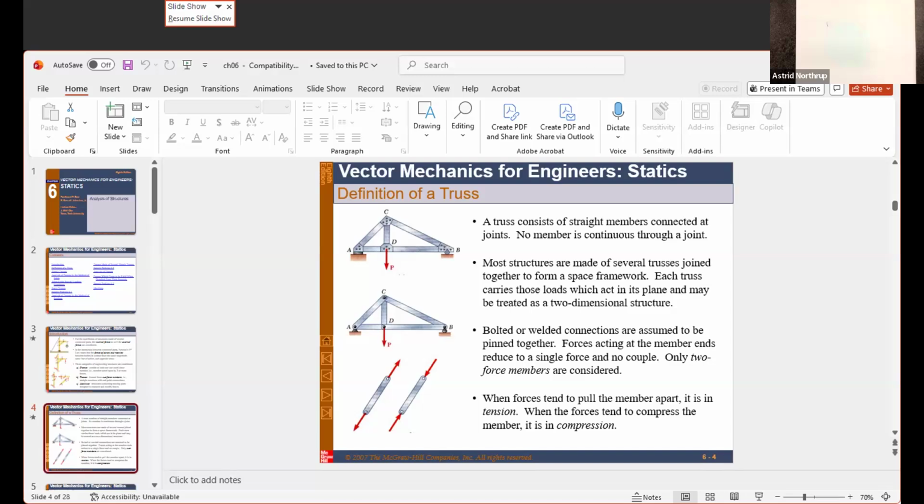The other thing is that the force is either pull or push on the structural members. So the elements of the truss are called structural members. Where they come together are called joints, and where they come in contact with something else are the reactions. But as I had said before, the direction of the load borne in a structural member has to be along the structural member.